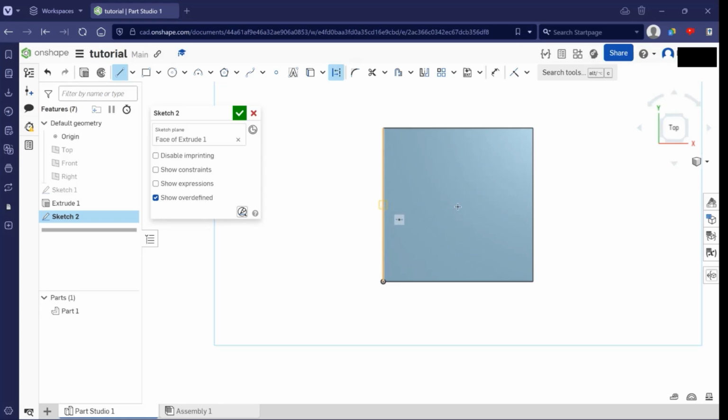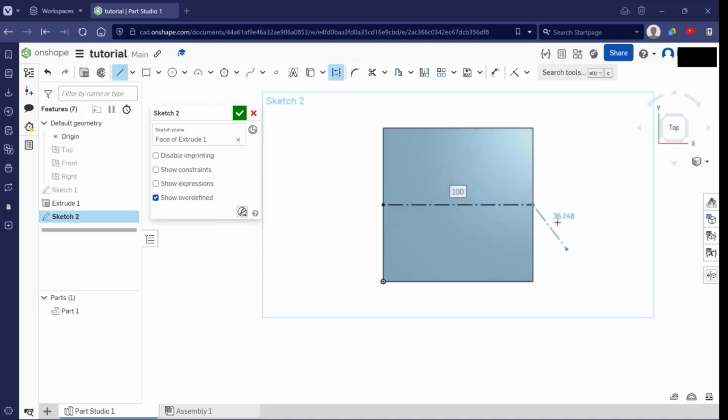And now, if it's horizontal, it will snap in place and it will show a horizontal line. Want it all the way to the other midpoint, right? So that's also horizontal. Let's put it on the midpoint. And as you can see, it's already black because it's already touching two things that are already defined, and it's also in the midpoint, so it cannot move, right? It's completely defined.